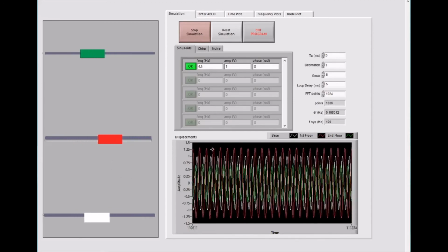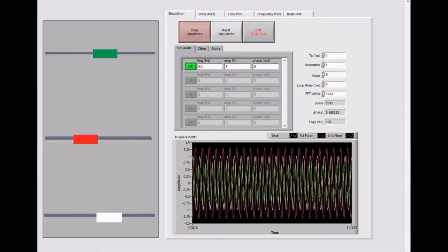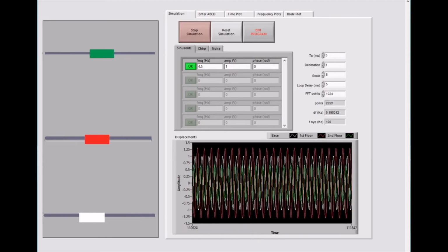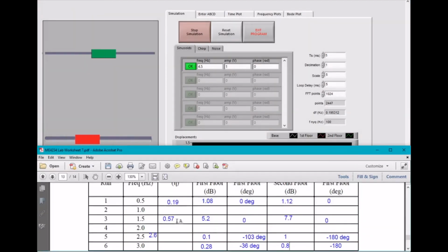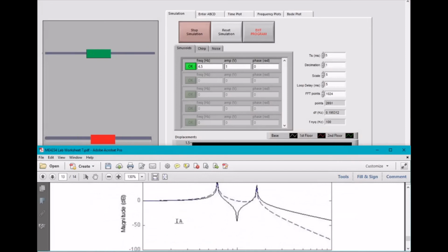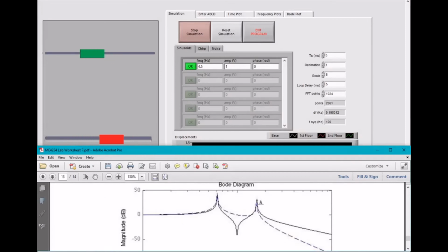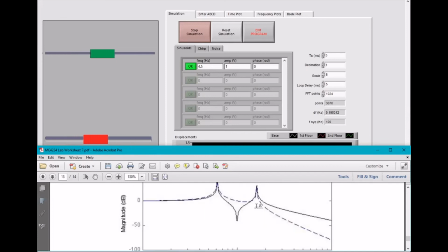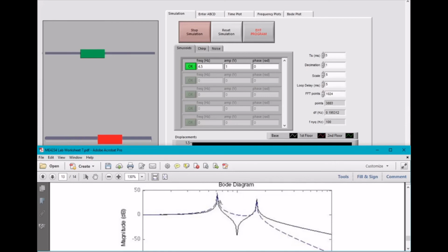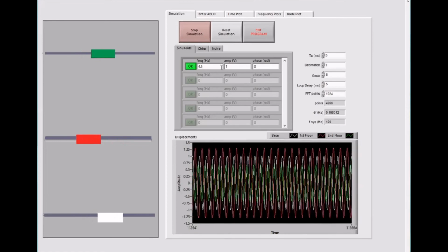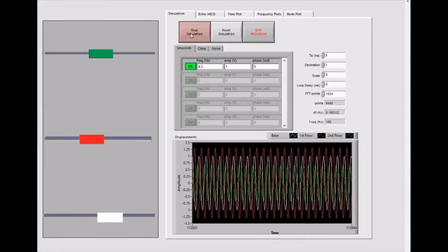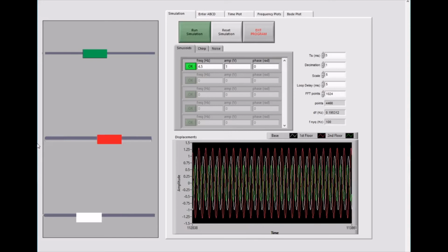One thing to note, even though your Bode plot can predict infinite amplitude, it can't actually happen. Why? Because we have damping. It doesn't go to infinity, and not only that, this width turned out to be narrower than the width for the first resonance. So it's actually hard to get large amplitude vibration for the higher modes. So this is when you have the frequency of 4.5.